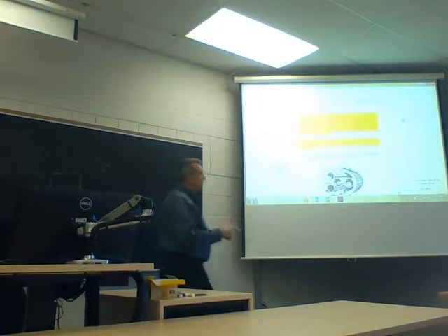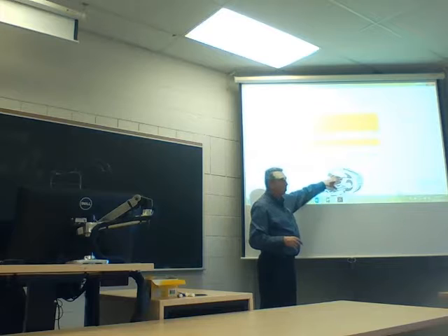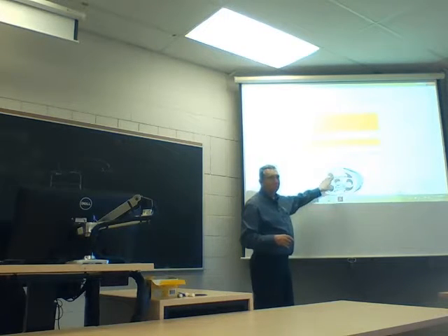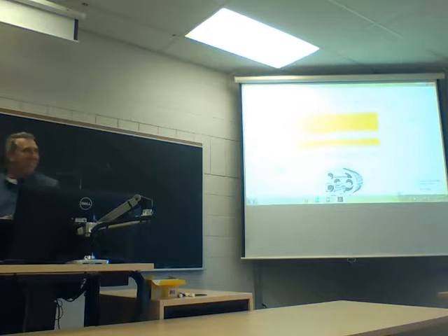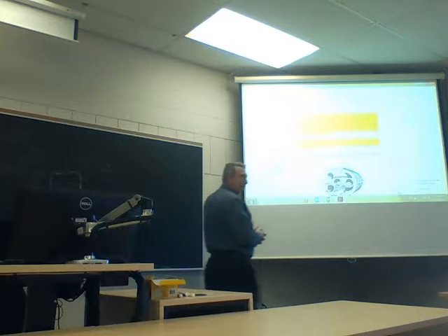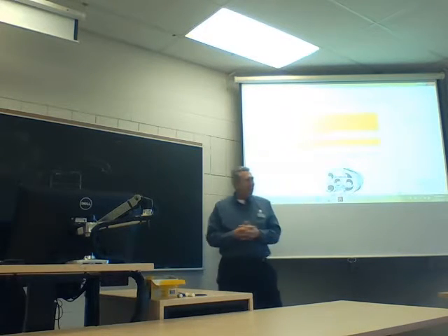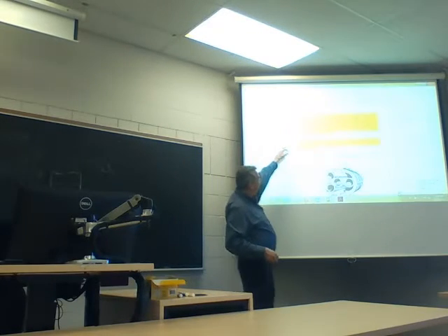So the one does drive the other, not by meshing together, but there'll actually be an outside gear that drives them, okay? It looks like it's rotating the rotor. It absolutely looks that way. I agree with you 100%. It doesn't, but I agree with you. One rotor is driven directly by the driver, the other is driven through timing gears or chain.